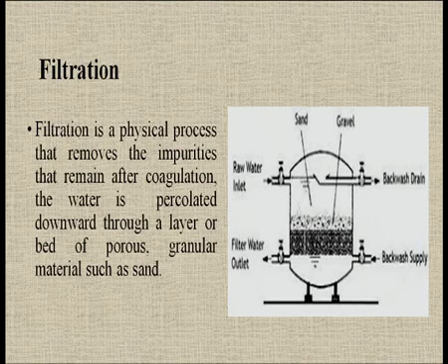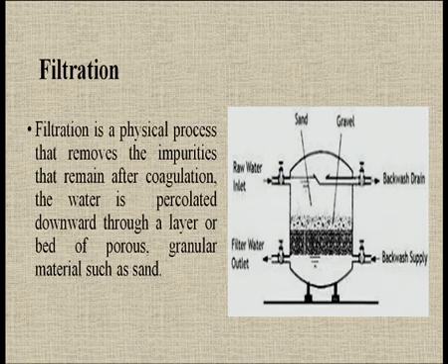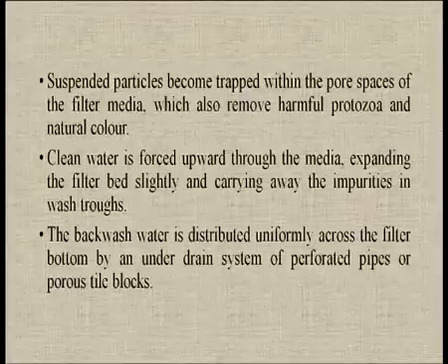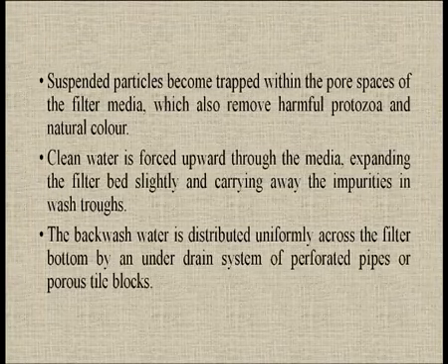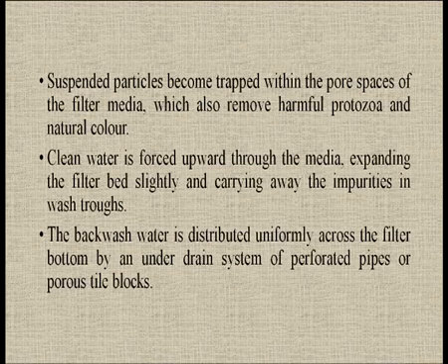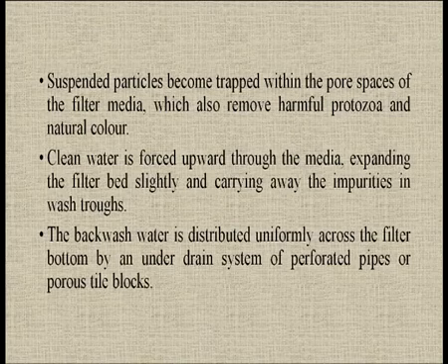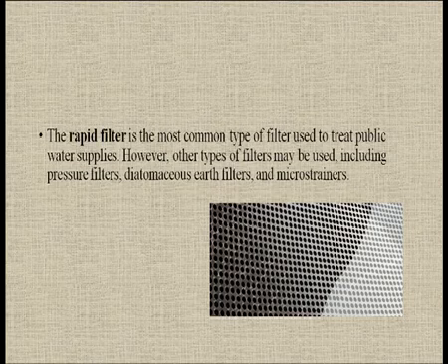Filtration is a physical process that removes the impurities that remain after coagulation. The water is percolated down through a layer or bed of porous granular material such as sand. Suspended particles become trapped within the pore spaces of the filter media, which also removes harmful protozoa and natural color. Clean water is forced upward through the media, expanding the filter bed slightly and carrying away the impurities in the wash water. The rapid filter is the most common type of filter used to treat public water supplies.